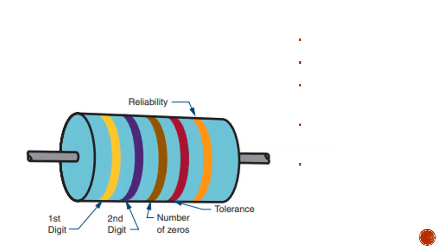A resistor may have a fifth band, as in the figure. This band indicates the reliability of the resistor. It tells how many of the resistors, per thousand, will fail after 100 hours of operation. Generally, when there are 5 bands on the resistor, the same amount of body color shows at each end. In this case, look for the tolerance band, position it on the right, and read the resistor as described previously.